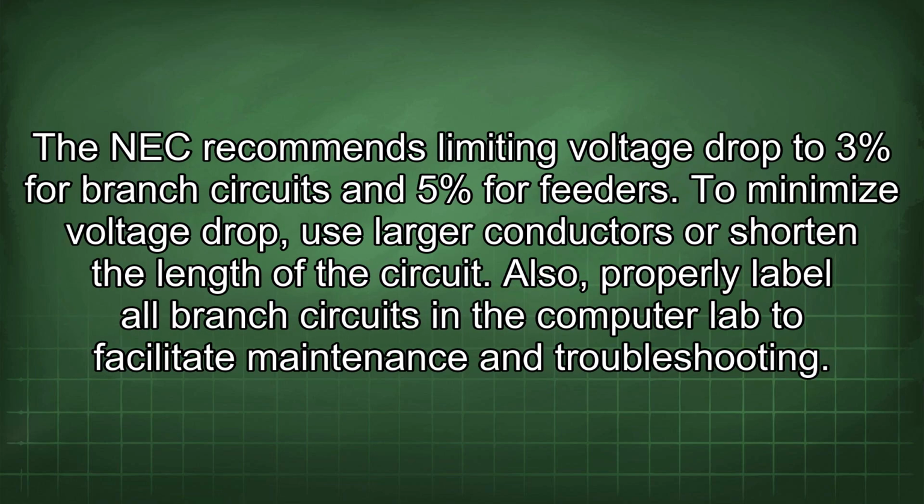The NEC recommends limiting voltage drop to 3% for branch circuits and 5% for feeders. To minimize voltage drop, use larger conductors or shorten the length of the circuit.